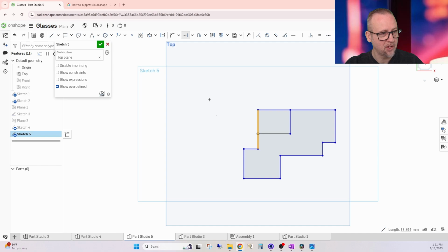Now, if I don't like that, I first click off of it, and I'll hit Control Z to undo, or I can hit the back right here. So that would take me back. So it shows me this is blue, which is not constrained, and black is constrained. Okay. Let's show you different things. All right, it's not going to let me grab, and it says this is parallel to the other side.